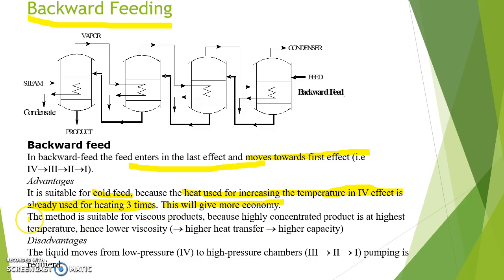The next advantage is this method is suitable for viscous products because highly concentrated product is at highest temperature, hence lower viscosity. A disadvantage of this method is liquid moves from low pressure to high pressure chambers, so pumping is required.